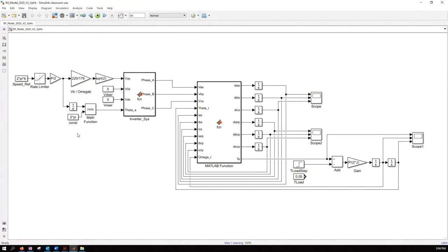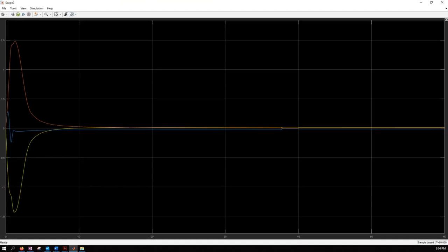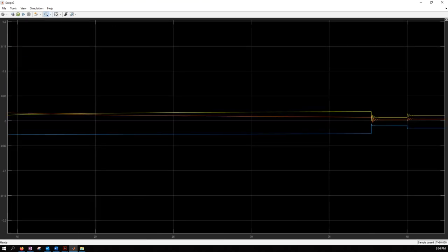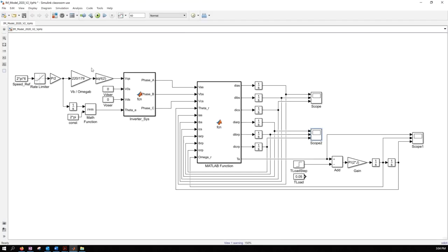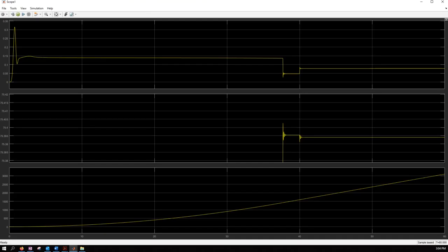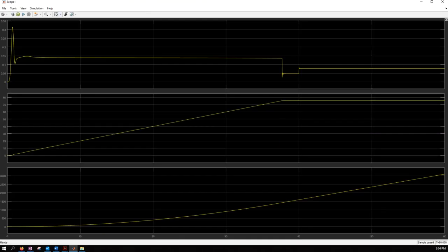Let's see what we have in terms of rotor currents, right? So rotor currents, very nice. See? You can see that they are still low frequency. Initially, you see a lot of current, but eventually they slow down. They are very, very low frequency. If you look at the torque, right? See, it's maintaining torque at a fixed value, and then you can see that it's somewhat changing after this. So this is after reaching the synchronous speed. It's lower, and then when we change the load, it's following.